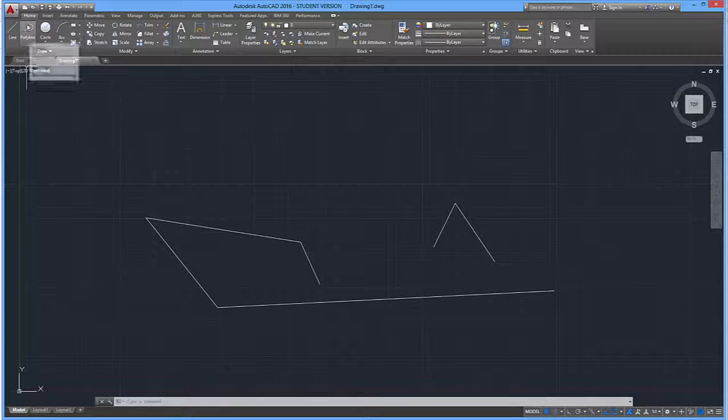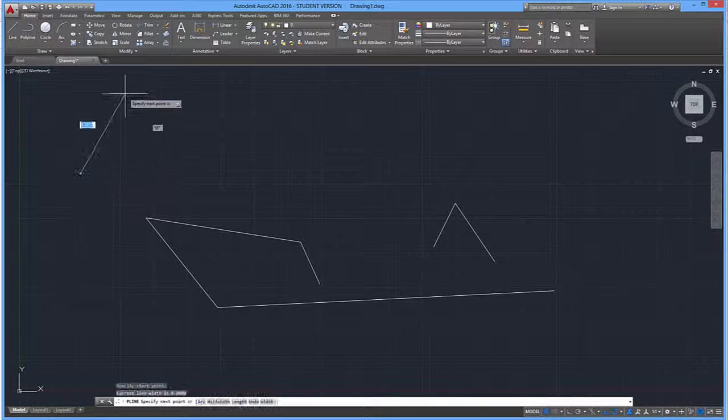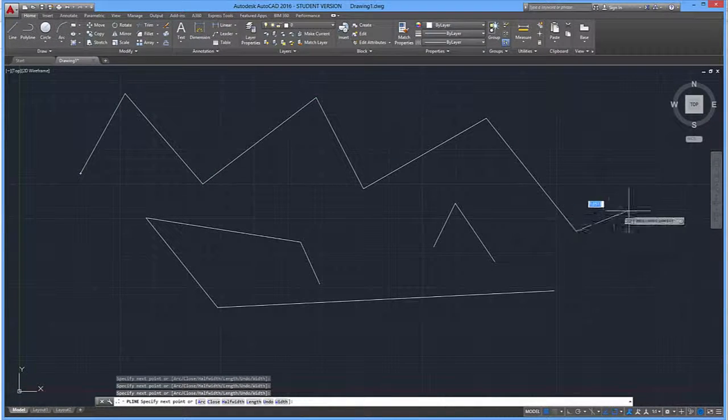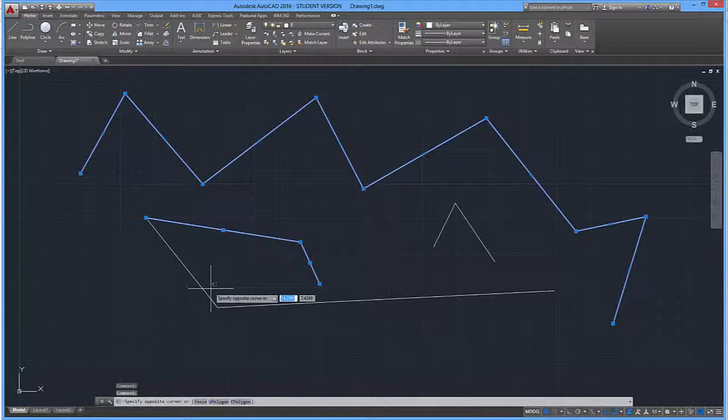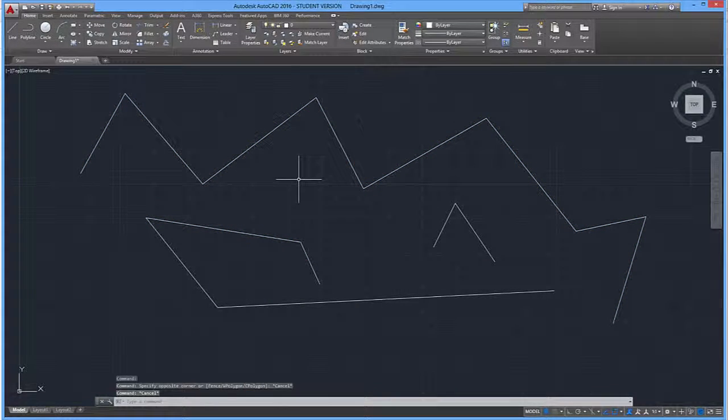We also have what is called a polyline, which is unique to AutoCAD, where you can draw out a line, and when you select the line, everything is selected. So it essentially acts as one object. And this is great when offsetting a line because you don't have to select every portion of the line. You just select one, and then you can offset the entire line, meaning duplicate it and move it. Or it's just easier to work with a lot of the tools up here.